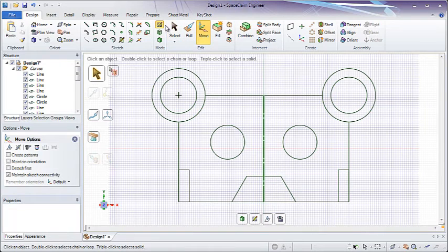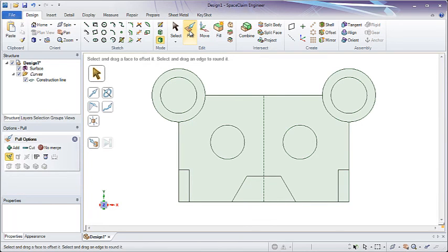And when we're going from sketch to 3D, all of the lines and curves will form surfaces provided they form closed boundaries. For instance, this was a closed boundary versus a line sticking off into space. And you'll also notice the duplicate edges and the lines we've created are not important. These will create just one single edge in 3D, which again, I can go to by either clicking the 3D mode button or Pull.